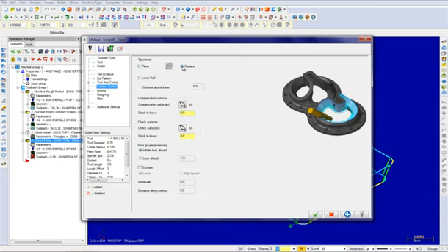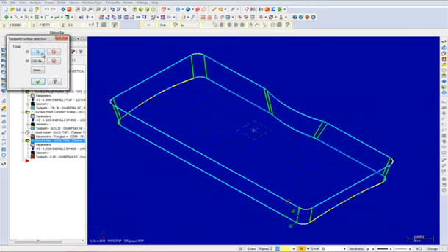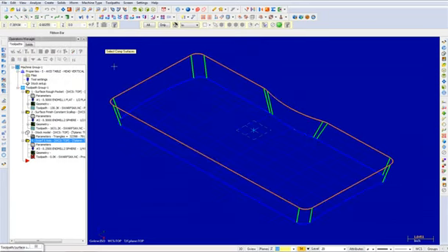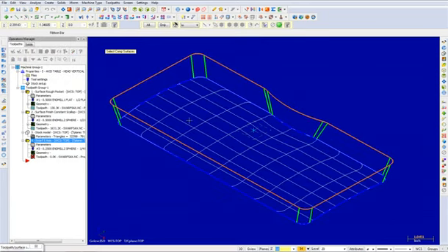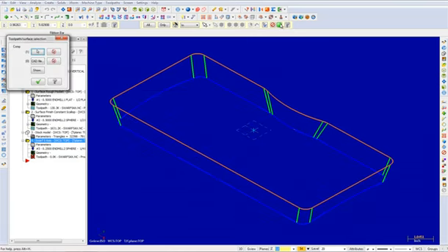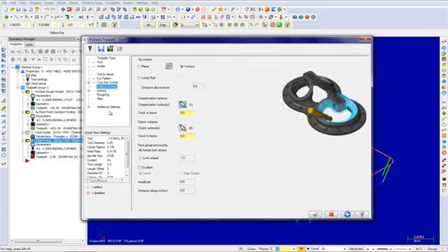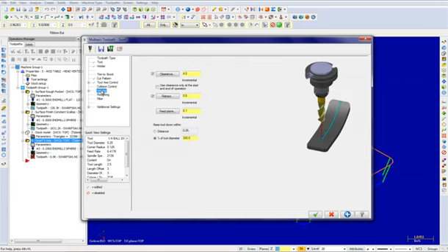Click on Surface to enable it. Then select the Select button to the right of Compensation Surfaces. Click on the Select button here to choose your surface, and select the floor surface here. Then hit the End Selection button. Choose the OK button. Then select Linking from the tree.